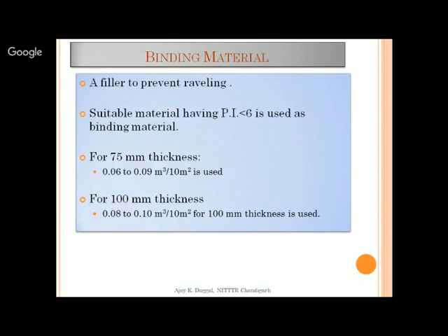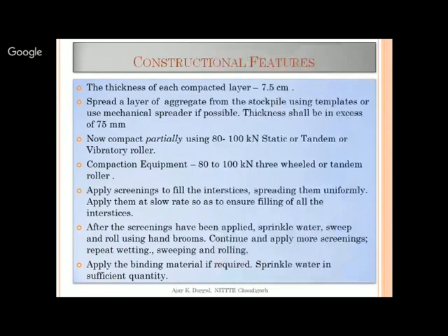But if you have something like 250, then I can have 1 layer of 100 mm and 2 layers of 75 mm each. So in this manner, you can always decide the thickness of the layer to be 75 or 100 mm. Now if somebody asks me that if the thickness is 285, well, it is generally not like that. It usually comes in differences of 50 mm. But if in any case certain constraints are there, then we can do the adjustments.